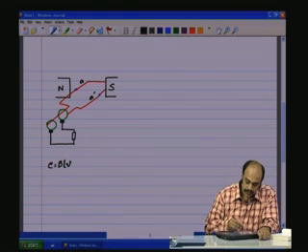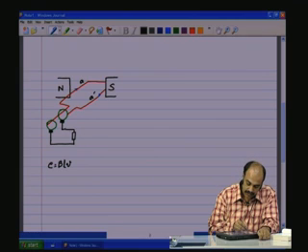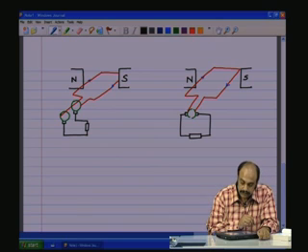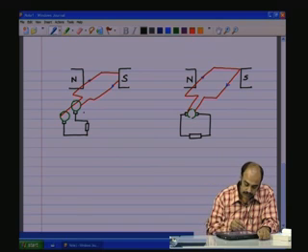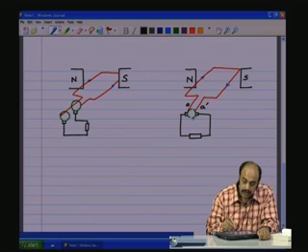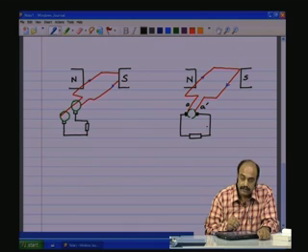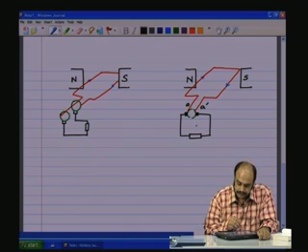And then we also saw that to rectify the waveform here, one could use split rings, rings that are split as shown here. You see, these rings are combined into one single ring, but it is split in between. There is no electrical contact between the A side and the A dash side of the ring. Of course, the brushes are making contact, they are fixed, and through spring contact they are going to take the current into the external circuit.